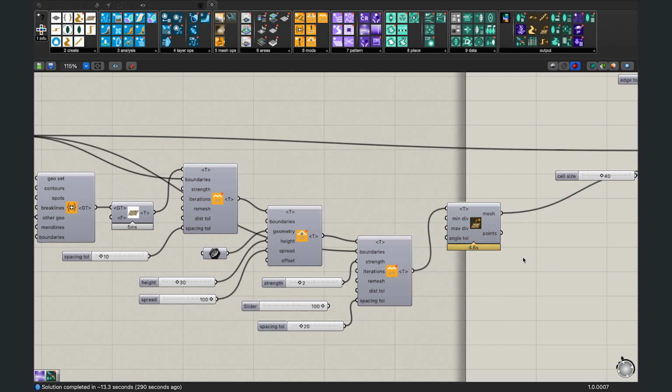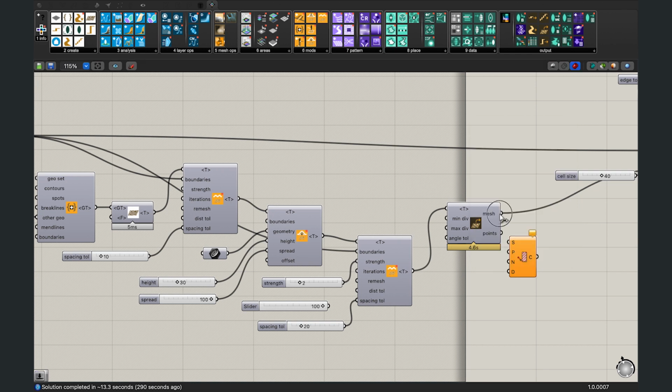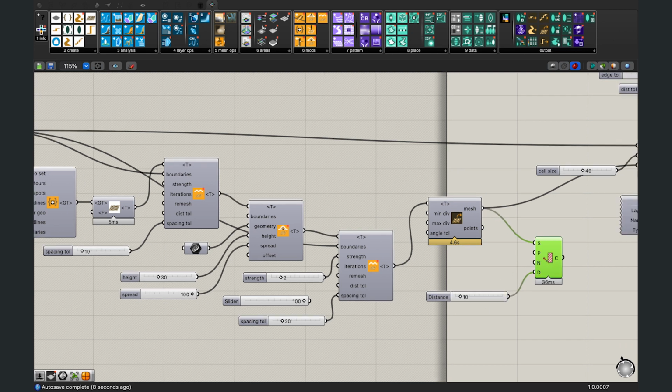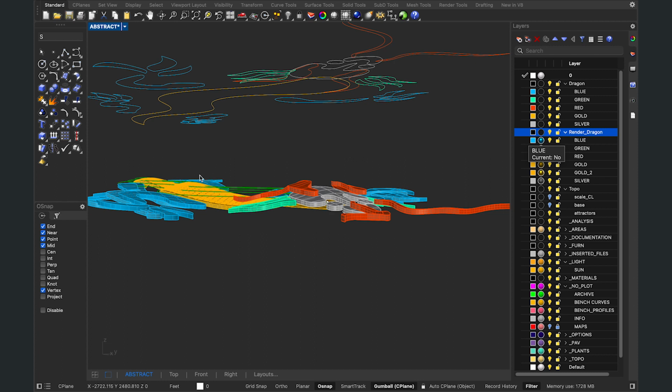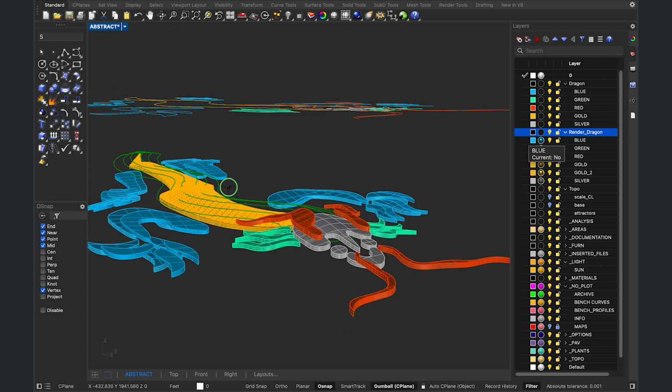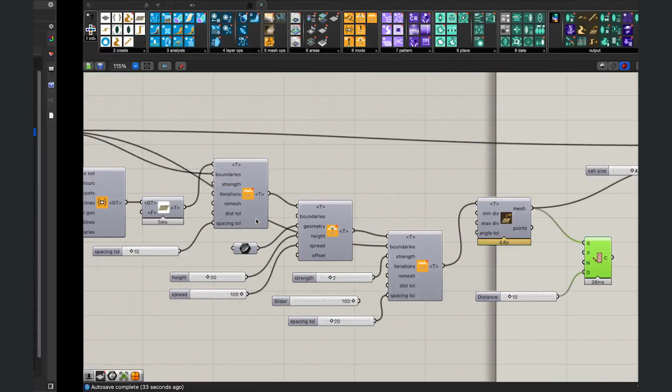Effectively, what we did is, let me just preview. Actually, I'll use contours to show this contour mesh, and then I'll do every 20 units because this is a rather large thing. Let me do 10. You can see that the contours are just an elevation that's flat, and it doesn't actually undulate the way the dragon ultimately ends up undulating. And so in order to get that curviness of the dragon feeling like it's moving up and down, as well as this curviness in plan, I used an equation.